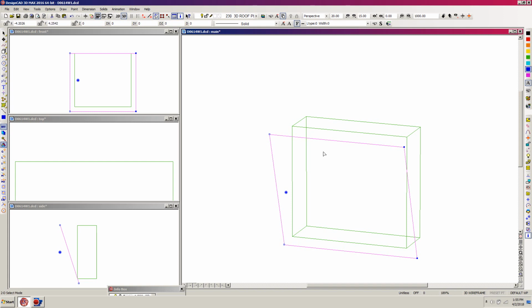So now what I need to do is mirror that along the y-axis, the vertical axis. So I'm going to set a handle on one of our wall corners because that's just an easy way to do it. Go over here to Set Selection Handle, click on it, right click at the lower left corner of the top of the wall. Boy, that's hard to say. Okay, right click on it, hit my scroll button to initiate the command setting my handle.